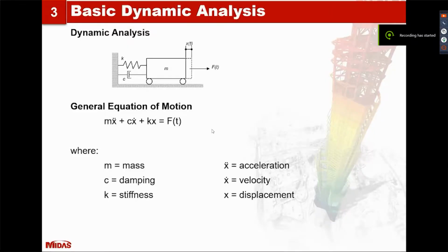From the free body diagram of this vibrating block, the differential equation of motion, or the general equation of motion, is as shown here, which is the mass times the acceleration plus the damping times the velocity plus stiffness times displacement is equal to a force with respect to time.